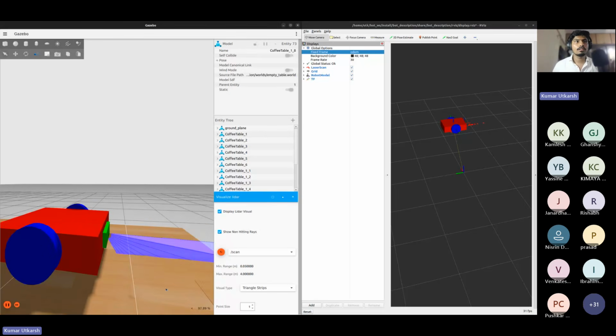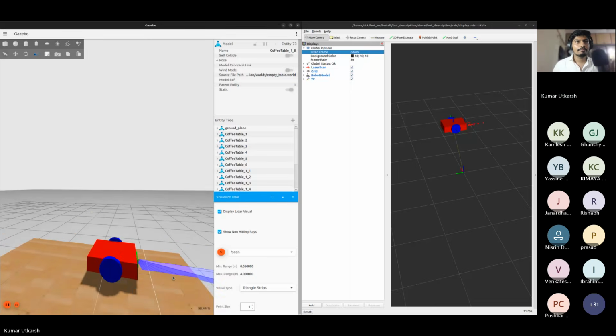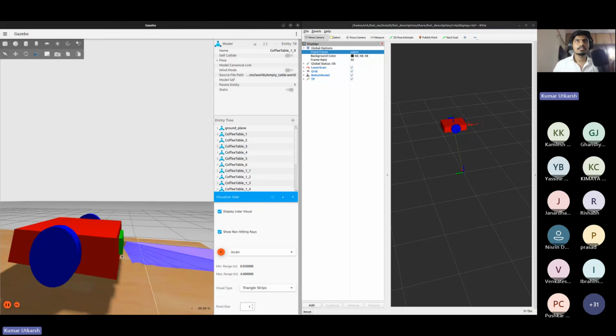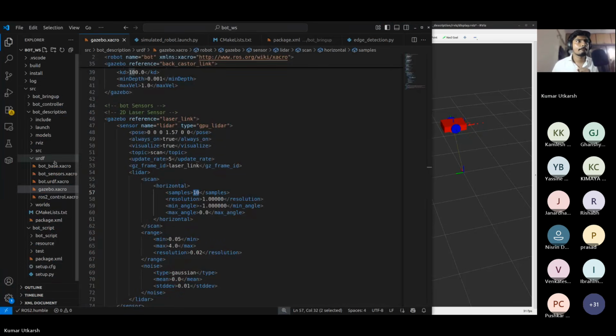So what I'm doing in the code is, the distance value is given in the form of a list. The Lidar every second, or every millisecond, whatever the time is, provides you a list of distances. In that, I'm selecting a specific distance value for upper rays, and this is the down ray, this is the up ray which I have named in the code. And based on that, I have written the whole logic. Let me show you the code once, then you'll understand it better.